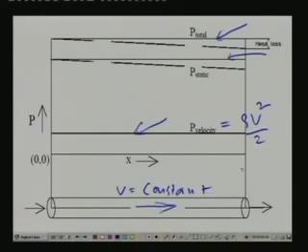Now, what is the effect if viscosity is non-zero? That means the fluid is viscous or it has finite viscosity. For viscous flow, the velocity pressure still remains same, because from the continuity equation, velocity at any point should remain same. So this horizontal line applies to both inviscid as well as viscous flows. So, velocity pressure remains horizontal only. Then what happens to the static pressure? Static pressure continuously reduces in the direction of flow because of the viscous effects. That means there is a loss of static head due to viscosity. So, you see a sloped dashed line for viscous flow.